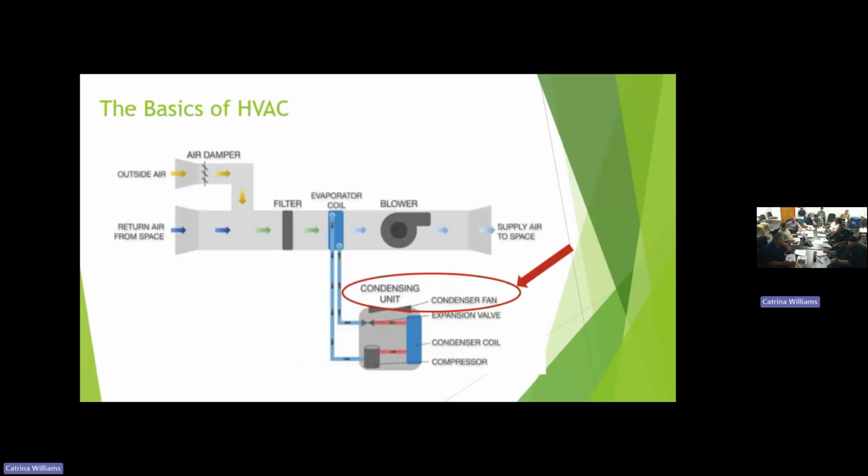So now we're going to start talking a little bit more on the cooling side. As we said before, you get a refrigeration system. The evaporator coils are in our unit, but remote of this and provided by other people is a condensing unit. And that's what gets the circuit going in the refrigeration cycle that pumps the gas through here.